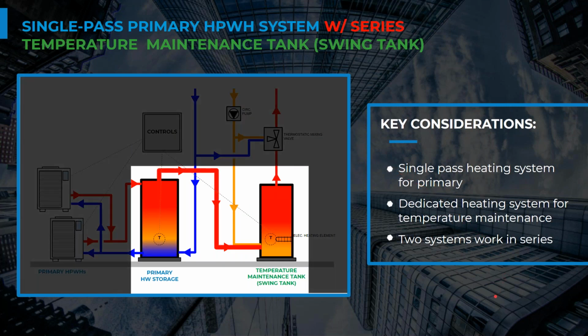So these two systems are working in series, but they're essentially dedicated. We're not going to mix our primary storage and create issues with our primary heat pump water heaters because we're providing a dedicated path for that hot water circulation load and those losses.